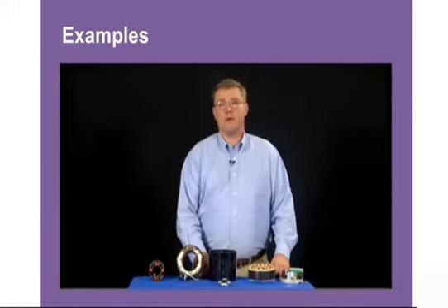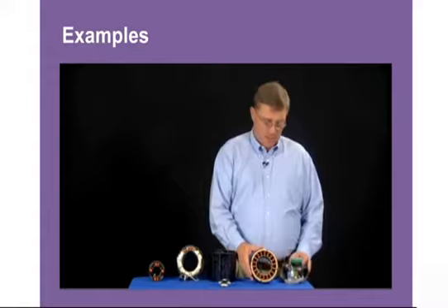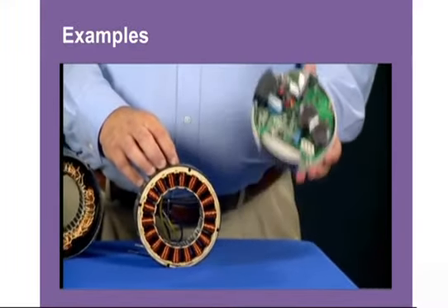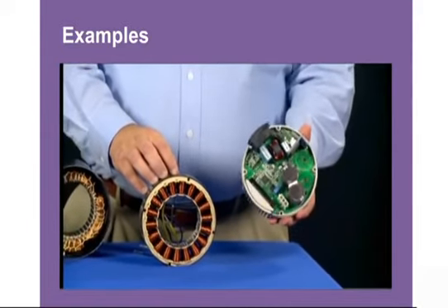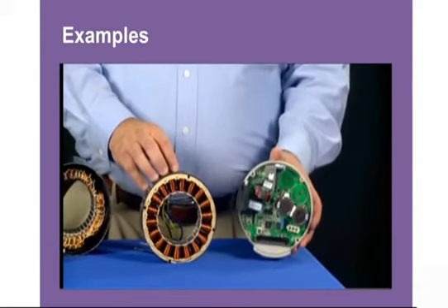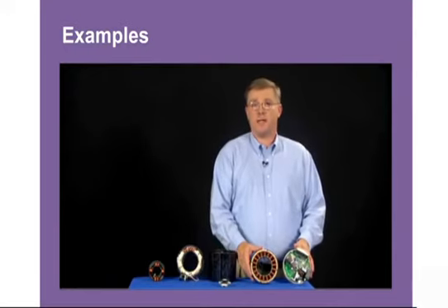The final type of motor is an electronically commutated or ECM motor. These types of motors are a permanent magnet DC motor that have a control board that runs the motor. These types of motors are more efficient in HVAC applications and typically a good retrofit upgrade replacement for a permanent split capacitor motor. An original equipment manufacturer OEM ECM motor is typically proprietary on the control board to the programming. Thus, OEM ECM motors typically need to be replaced by an OEM ECM motor.